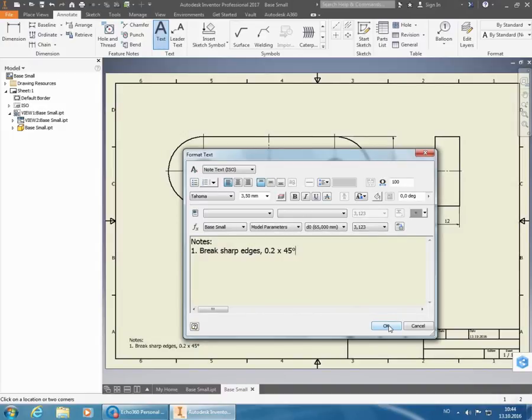When I worked in Imenco, the first note was usually always that the material certificate was supposed to be conforming to a certain standard, so that whoever manufactured the part also had to attach a material certificate for it according to a certain standard, so that we could prove that the material was what we said it was. That is a very common thing to require in the offshore industry.